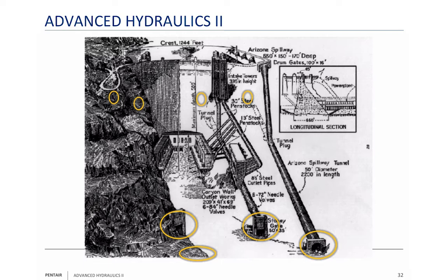So they dig these tunnels, 4 of them, 2 on the Arizona side, 2 on the Nevada side, and they say, okay, now let's build a dam between them. So they put a dam over on one end, which forced the water through the tunnels. Then they put a dam on the other end to force the water downstream. That meant that the area between the 2 dams, they could put a pump in there and pump it all out. Okay? Now they can dig down to bedrock and start building the Hoover Dam, and that's what they did.